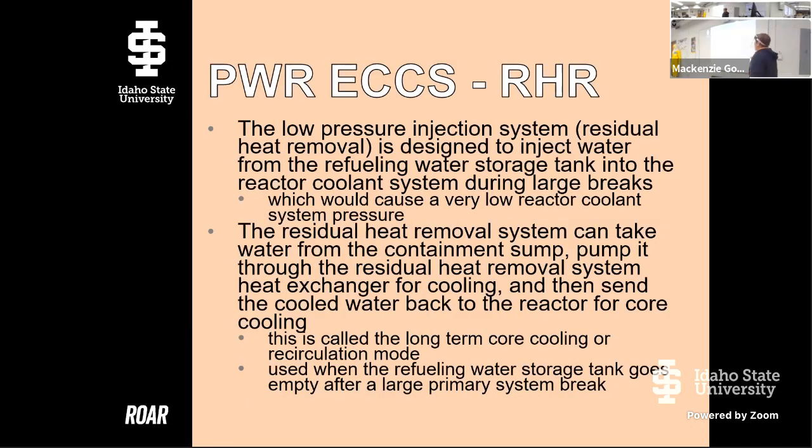And then of course we've got the low pressure injection system and our residual heat removal system, which deals with residual heat. You've got its own heat exchanger. This is also called long-term core cooling or recirculation mode. So if you have some accident where you can't restart your reactor, put that primary system back on, but you need to keep it in a safe, cool, shutdown position, this is the system that's going to be used.